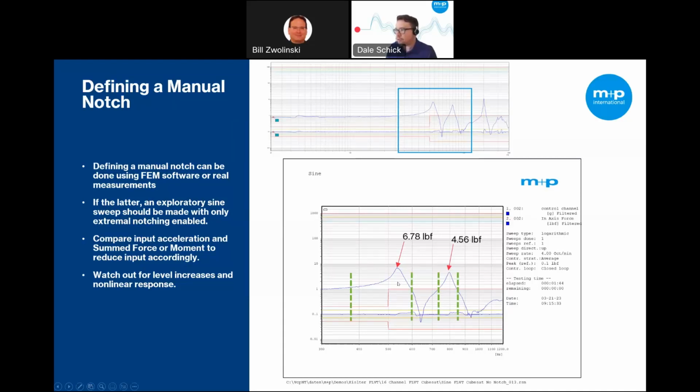Wherever it starts to deviate is about where we would want to start considering entering into our bathtub notch. So you can see for this first mode, this is a much slower slope as the mode is much more highly damped. And then for the second one, this is much more aggressive. So this second one, we would probably design to be much skinnier, so to speak. And this is where we're going to consider our initial slope. Where the blue dotted lines appear is where we would flatten the bathtub to its lowest level.